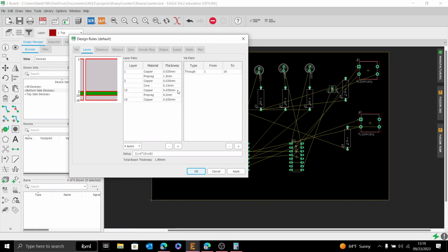This is your layer thickness. Unless you know you need to worry about it, don't worry about it, because the manufacturer we're going to use, PCB Way, has their own pre-configured thickness. They don't actually care what we send them unless we explicitly tell them, hey, I want this to be this. And so a lot of this comes down when you start getting into more advanced PCB layouts. It's a bit more than I can cover. I don't even know the full depth of it. So we can just ignore this. So we'll come back eventually and show you the difference between using a 2-layer board and a 4-layer board, because there is a slight difference with how I would handle things with 2 versus 4 layers.